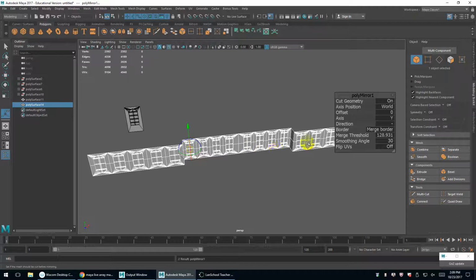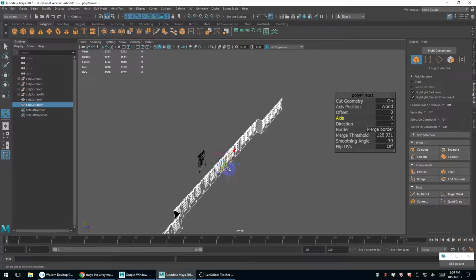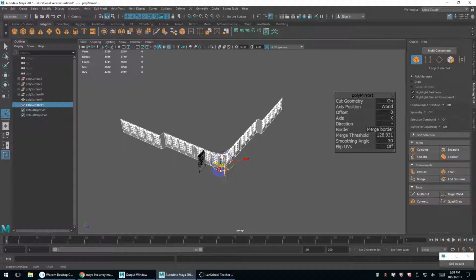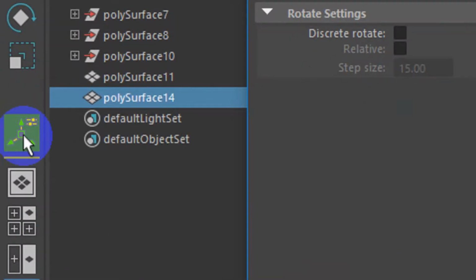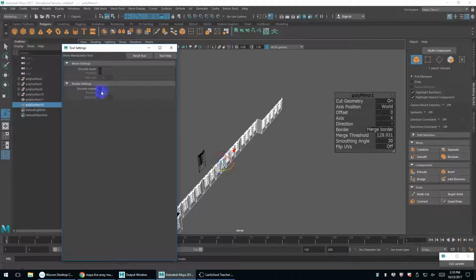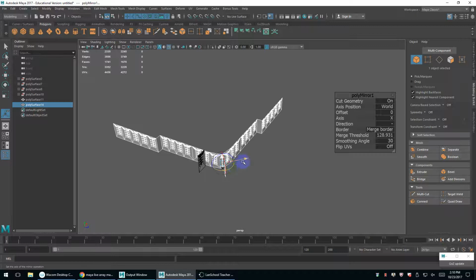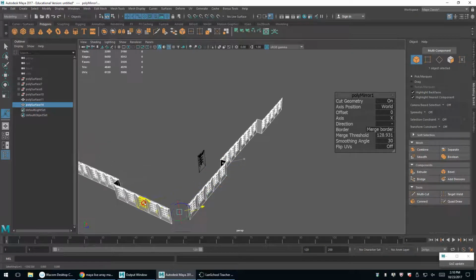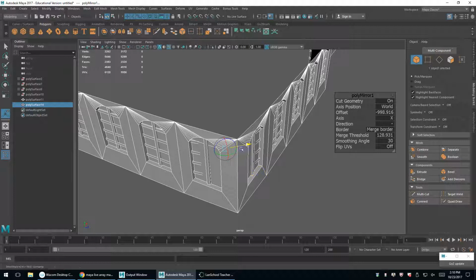So if I go mirror again, right, I can try to switch the, I'll go back to the X axis, and then rotate. And you want to make sure you've got an angle snap turned on. So I'll double click the manipulator tool, which is active over here on the left hand side. It's right in here. So this is when you're in poly mirror. I'm going to go discrete rotation. 15-degree snap is okay. So I'm going to rotate this thing, which should be, I guess, 45 degrees. And then I'll move this arrow out. So I really want to just kind of get into the corner to snap.